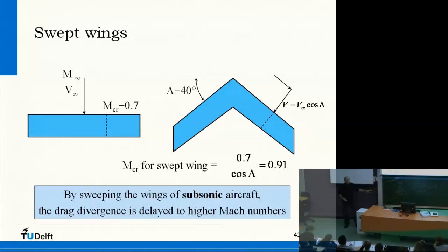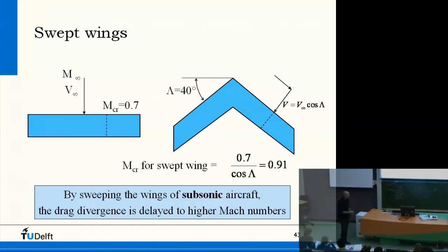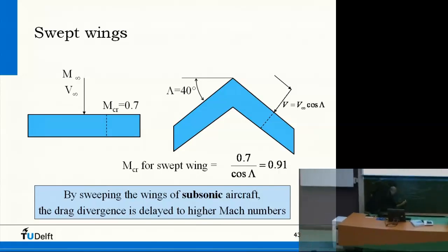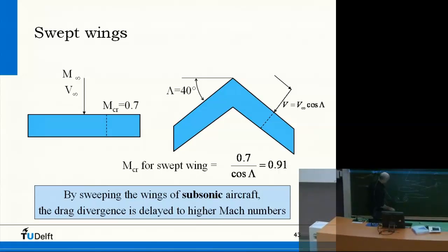So that's a little bit different concept, and these are very thin as well, very sharp here. This vortex that comes from the leading edge is very vast. If you look at it from this side, you will see something like this. And so this gives very, very low pressures. This is the lift that is associated with it.